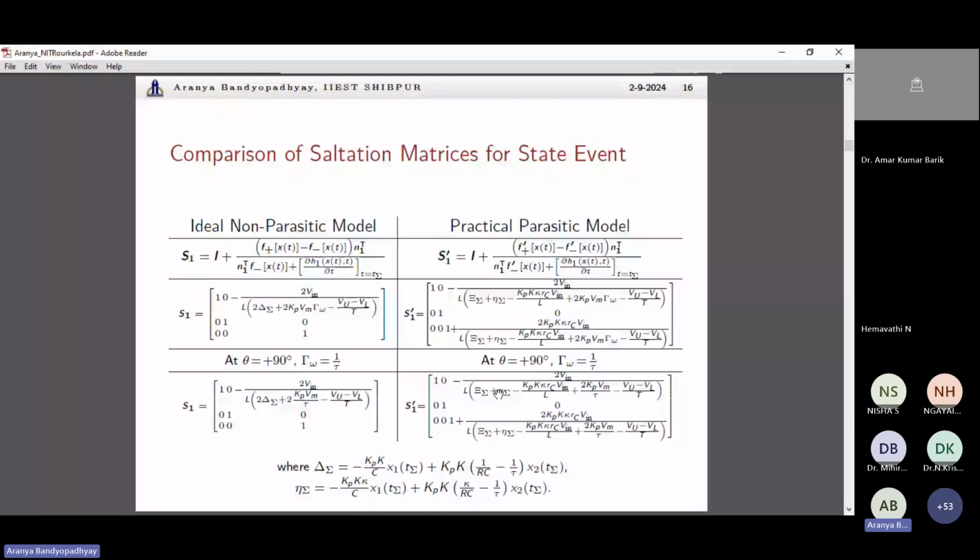In the case of the PFC boost converter, the first case of instability manifests at zero crossing, at 0 degree angle. Now, there are no theoretical proofs for it, but only based on experience and observation, it has been fixed. So that's why we are going to fixate our case for this phase angle only.